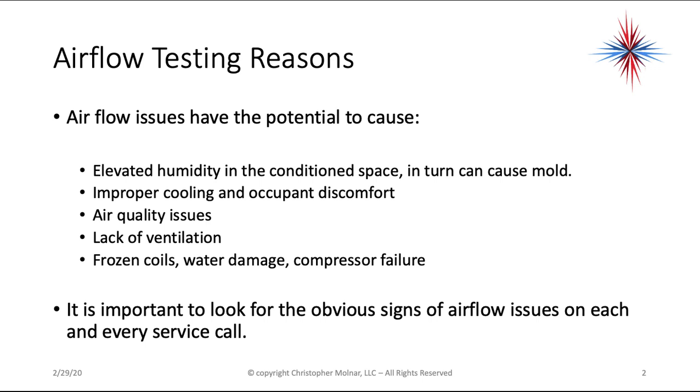Airflow issues have the potential to cause elevated humidity in the conditioned space, which in turn causes mold, improper cooling and occupant discomfort, air quality issues, lack of ventilation. It can also cause frozen coils, which in turn can cause water damage and compressor failure. It's important to look at airside issues for obvious signs of airflow on each and every service call.